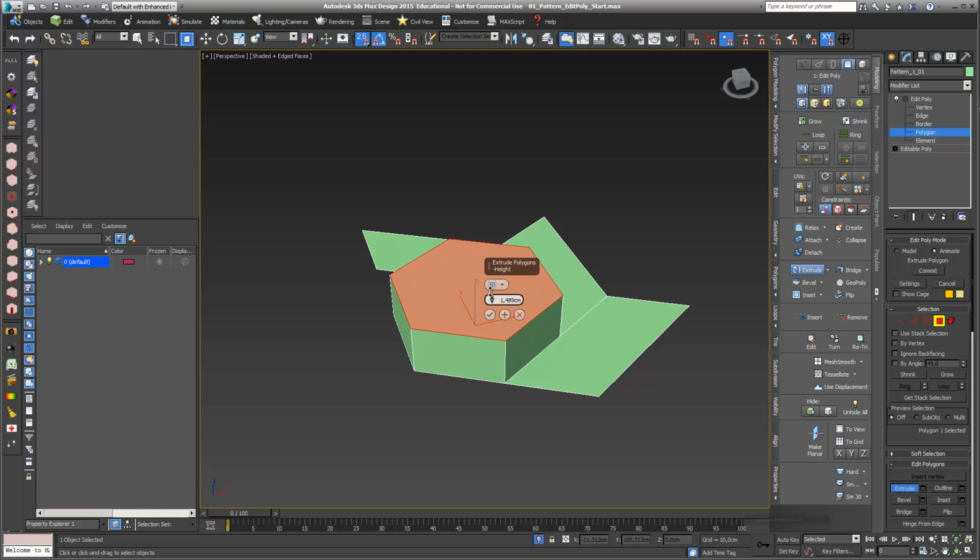And if I extrude this right now, for example in this negative direction, and close this, I always have the option to go back into my settings. So when I just model something in Model mode, I don't have the option to come back and change the parameters. If you switch to Animate, you can go into your settings and you can always change them on all levels.